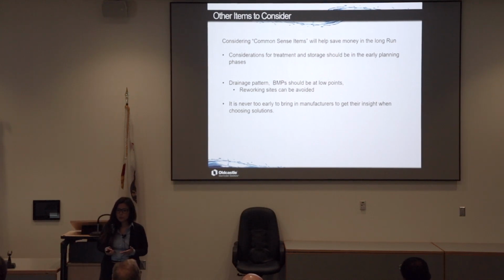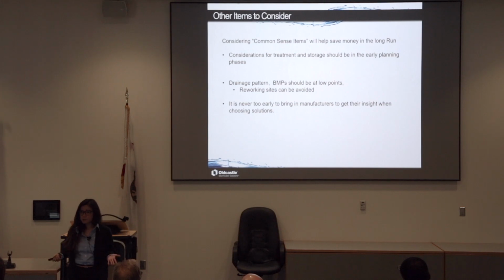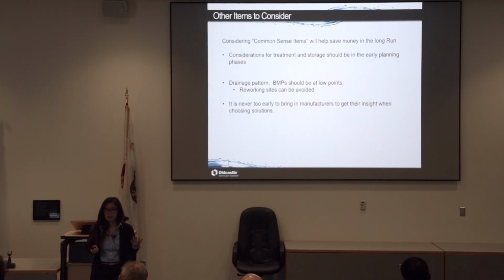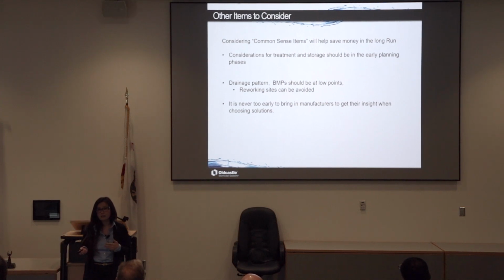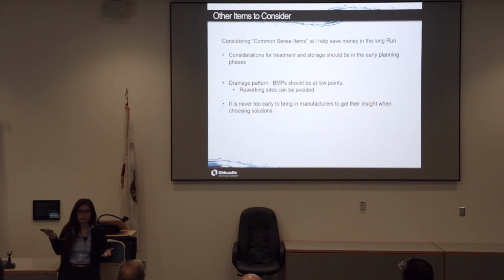Also, it's never too early to bring in an expert or a manufacturer to give you a second look at what you're designing. Sometimes I get projects way later in the construction phase, and the design is not done correctly. For example, a system will have over 6 feet of backfill when the system can only handle 2 to 5 feet of backfill.